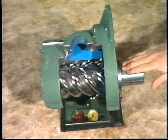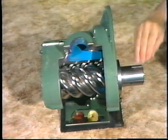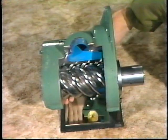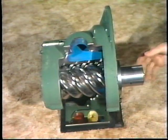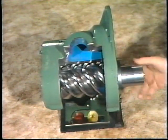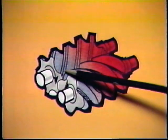Here is the drive shaft, and the inlet and outlet ports here and here. As you can see, these two helical screws mesh and rotate together. As air comes in, it gets trapped between the screws. Since the volume between the helixes decreases as they turn, the air is compressed and exits at a higher pressure.